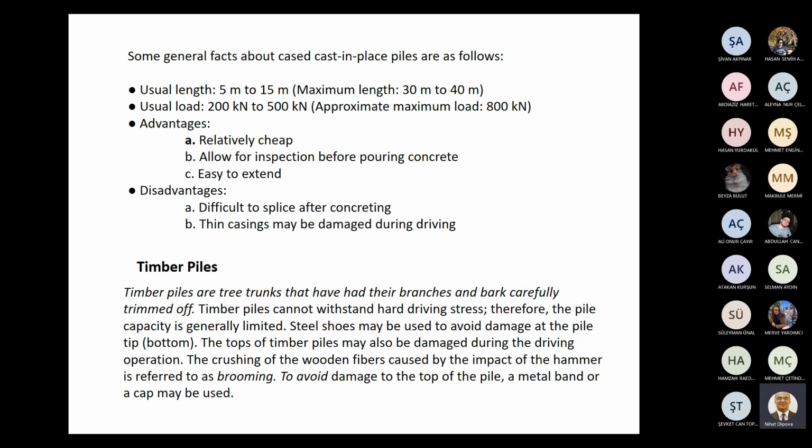So it's a natural material and used almost as it is. Timber piles cannot withstand hard driving stresses. Therefore, the pile capacity is generally limited by driving capacity.